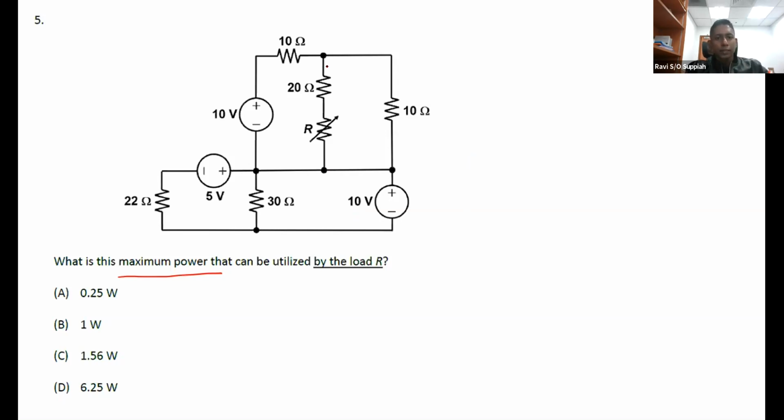Okay, so if you look at this circuit, when I open circuit this, so if this is now open circuit, what do you see? Okay, so to analyze this circuit, we must understand the way it is connected. You can see that these 3 points are actually shorted together, without any component in between. So this actually acts like a common point that separates out this circuit from the rest of the circuit here. Okay, because when you have these 3 points as common, you can treat this part of the circuit as separate, and this part of the circuit as separate.